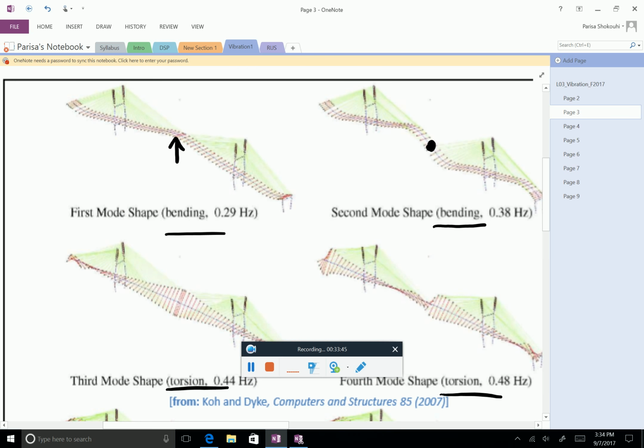Well, for each mode you do that, and that kind of tells you where the problems are. So, for example, if you see that the maximum difference is in the first bending mode, that could tell you that the problems are in the middle of your bridge. Typically, in that case, people try to go a little bit closer. Then you divide it into a number of elements, and then you go element by element, change things, and do this until you localize it.